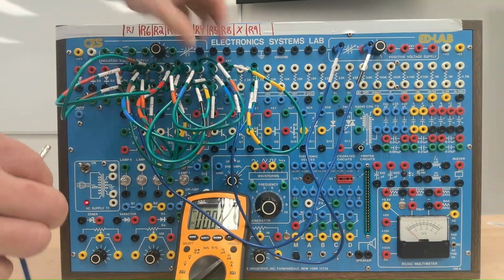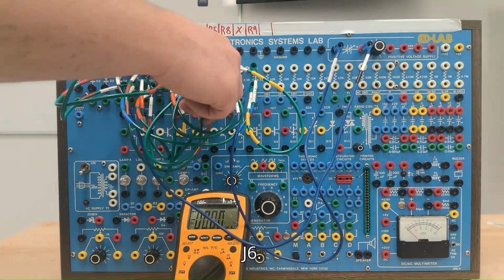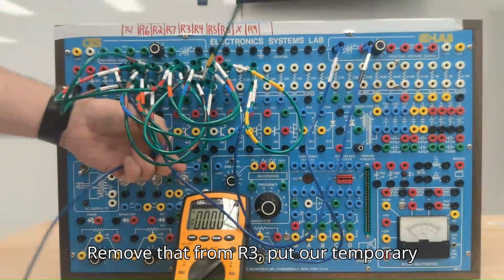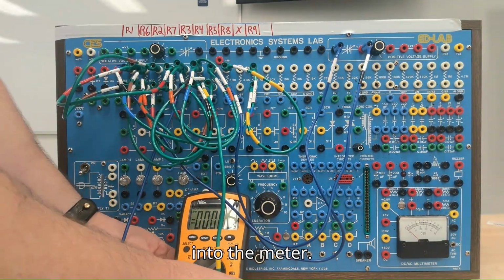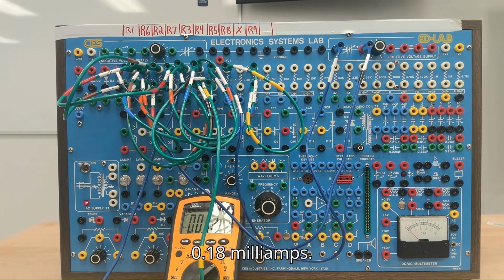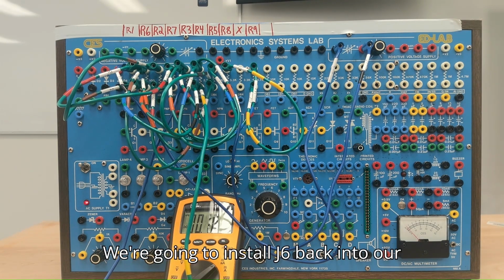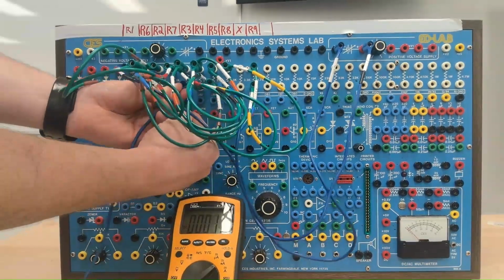Next, we want to read the amperage through J6. J6 is on the bottom side of R3. Remove that from R3, put our temporary lead in that same position, J6, into the meter. We'll go ahead, turn our trainer back on. The amperage going through J6, 0.18 milliamps. We're going to install J6 back into our circuit. J6 was on the bottom side of R3.